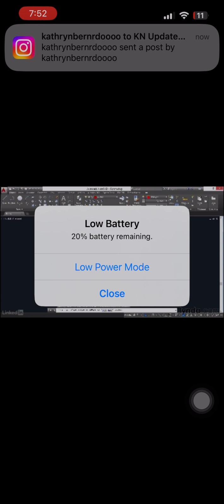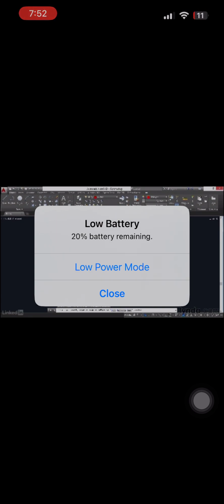I could click another object, say this line, and then either click above or below it to create yet another new object. I could select this object and offset it to the left, and keep doing that to create a series of lines that are all equidistant. When you're done, press Enter to end the command.